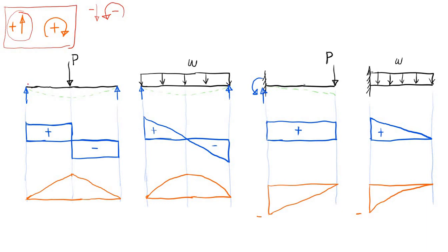Now, notice that we start from 0 here. This is our base. Since this is upward, then the force should be positive. And between these points, there is no change in shear. So the shear must be constant. And until this point load, then there will be an abrupt downward force. And again, we have here an upward force.